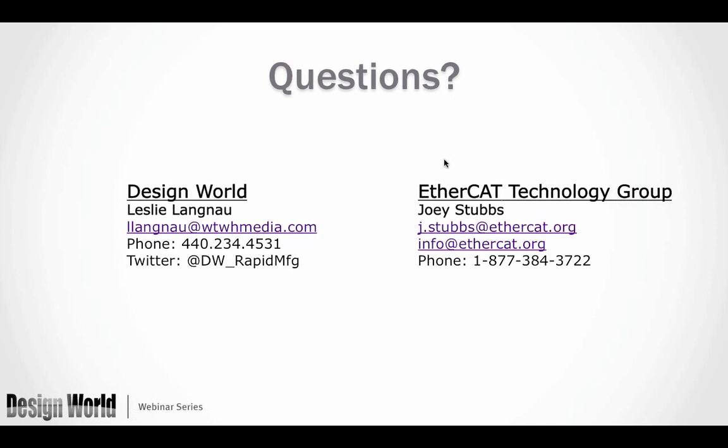Okay. And we have a follow-up question to the routing EtherCAT. He said not routing to the internet, but routing internally into subnet domains. You can use VLAN tagging with EtherCAT. So if you need to have individual EtherCAT networks coming from one master, you can use a VLAN switch and then specify which port the EtherCAT frame comes out of. Other than that, internally within an EtherCAT network, there's no routing of frames. That's what makes it so efficient and so fast.